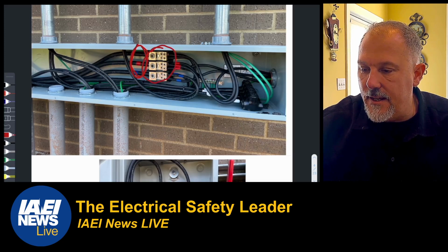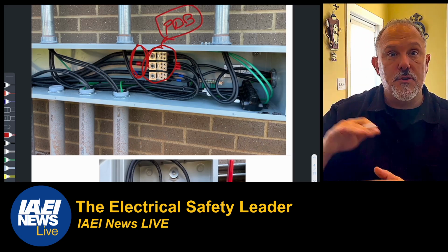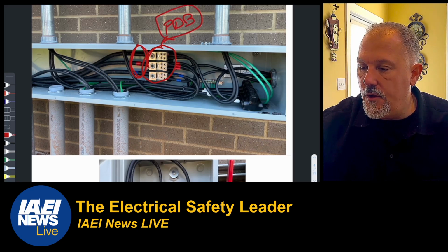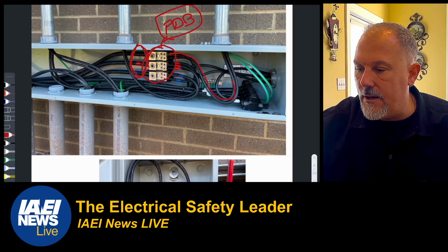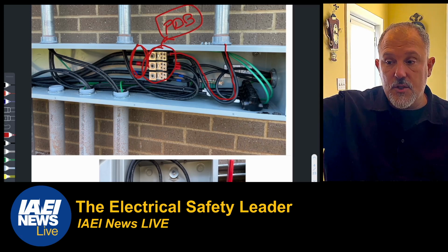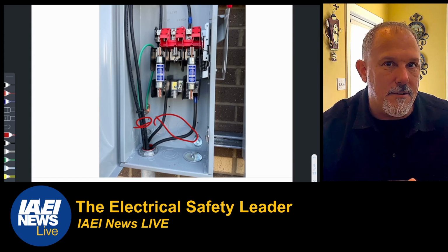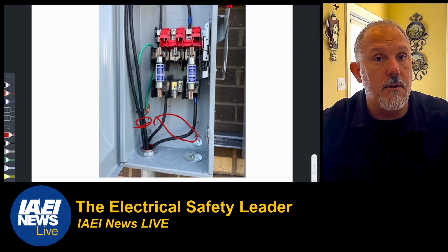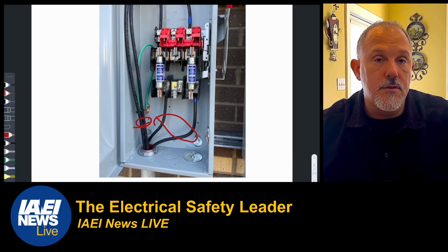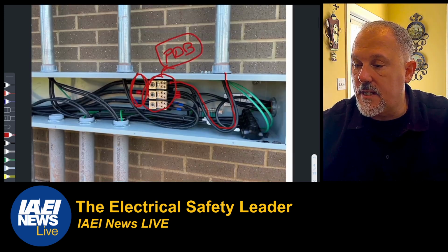And this is a power distribution block. Those are where your taps are taking off of. And you'll notice that the tapped conductors go out and they go up. There's two per raceway going into the switch, because these switches, there's your two coming in, and there's your gazintas and your gazaltas. So you got two coming into the switch and two leaving the switch, and you have two fuses because this is a single phase application. So that's basically what you got going on.